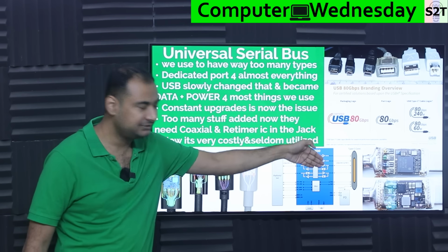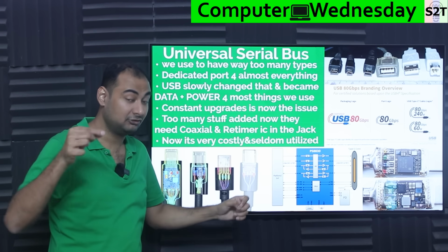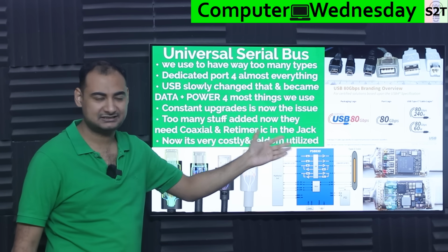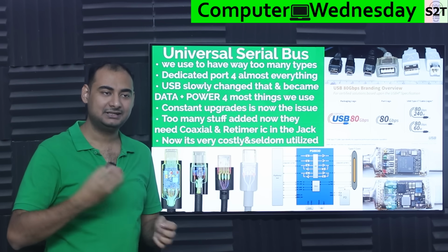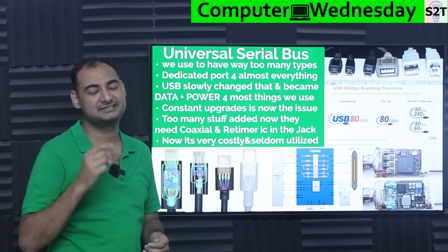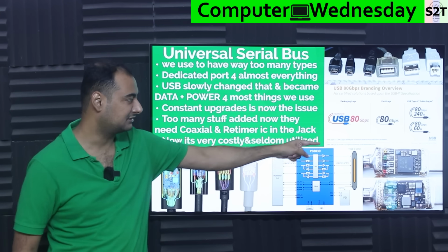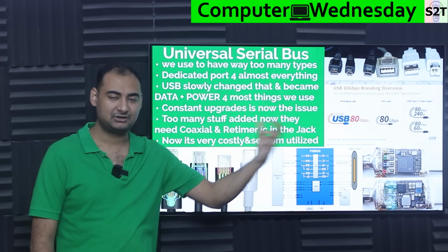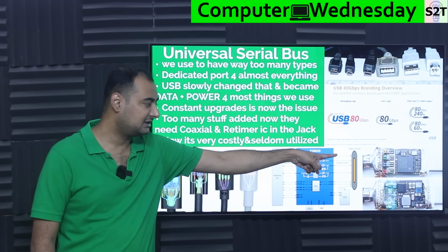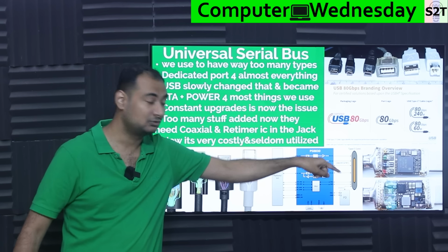Meaning we have to put a computer in the chip itself, as in the actual plug has a full-fledged computer. Let that sink in. So what does that computer do? Well, that computer takes the power, creates a power supply. That power supply feeds power to a ball grid array system that is a retimer chip. Basically, that retimer chip does the signaling because the connector itself is so noisy that if you try to digest data at 40 Gbps, it will not transmit very far. So it digests the 40 Gbps transmission and then creates a clean signal that goes through coaxial cable.